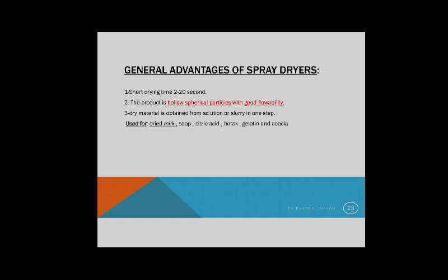General advantages of spray dryers: a short time, from 2 to 20 seconds. The product is hollow spherical particles with good flowability. Dry material is obtained from solution or slurry in one step. Used for dried milk, soap, citric acid, borax, gelatin, and acacia.